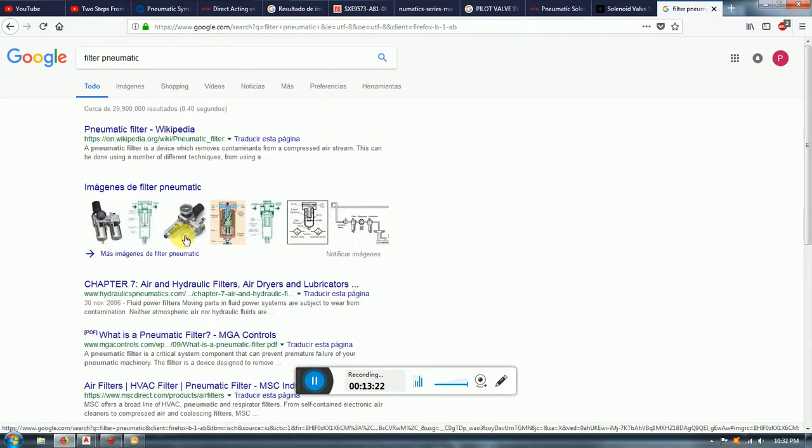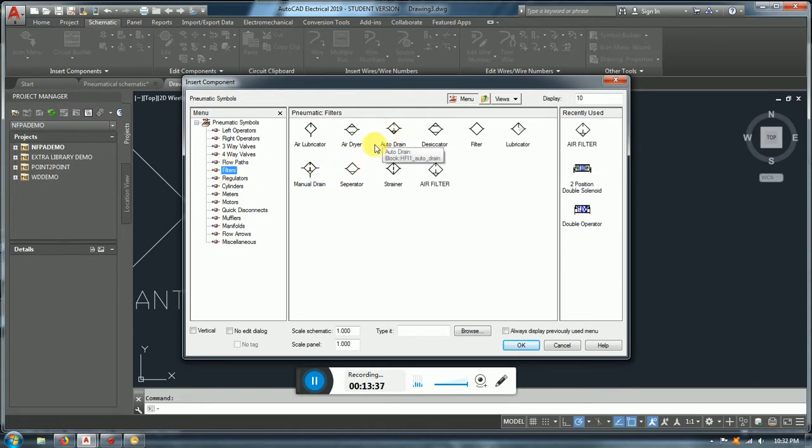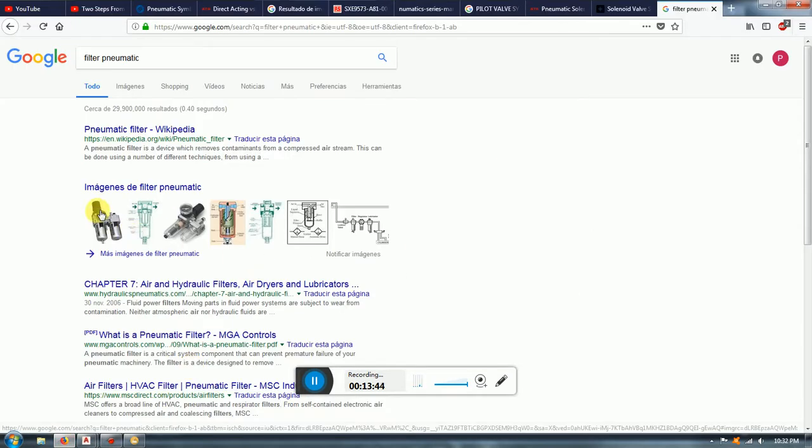Okay, this is the regulator. You get regulator and filter. Filter only filters particles. It drains through here. Could be manual or could just be connected, and it could be, how they call it, auto drain, I guess. Manual drain or auto drain. After that, we're gonna have the regulator. Okay, the regulator is that thing, okay, with that gauge. Okay, there is where you control the pressure.